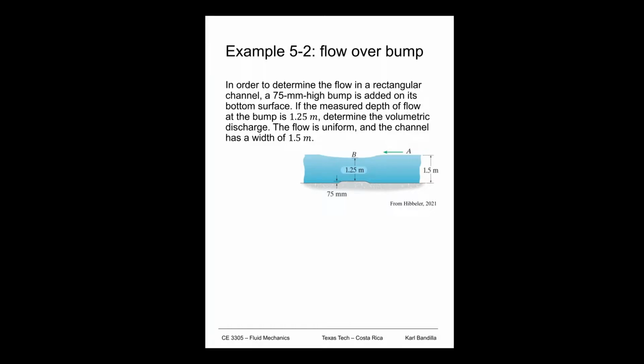First of all, we have to figure out, can we use our Bernoulli equation? What do we have to have? It's water, so it's an ideal fluid, so inviscid and incompressible, compressible but not compressible. We have steady flow. It doesn't say anything about changing over time. And if we look at a point right up there and one right here, they're on the same streamline, the streamline that goes along the surface like that.